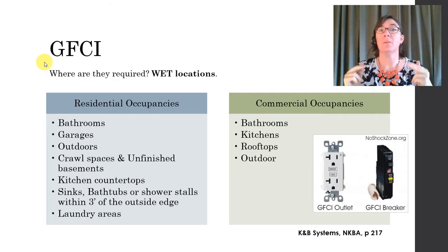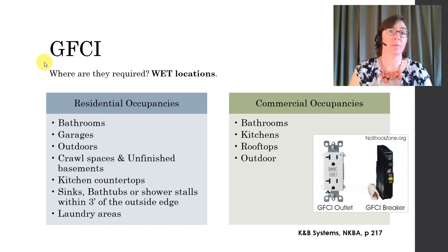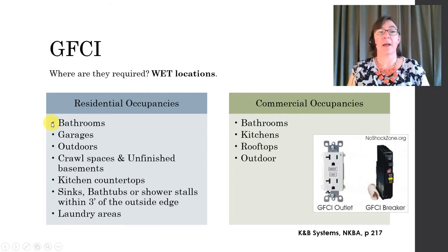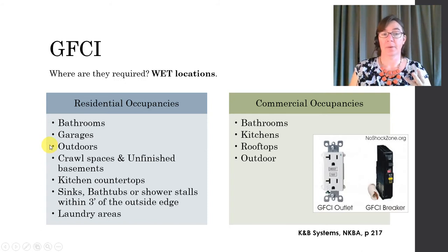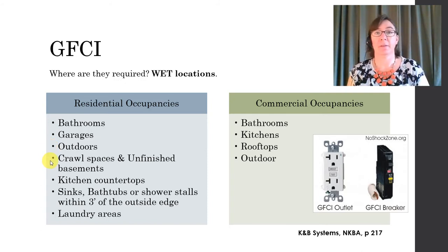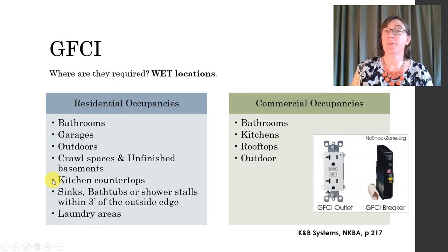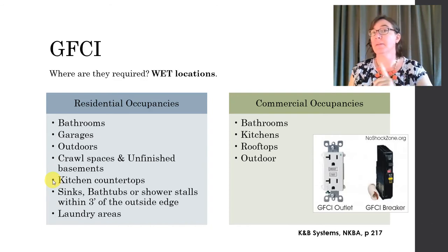They're required in all wet locations. For residential occupancies, which we're mostly concerned with in this class, every outlet in bathrooms, garages, outdoors, any crawl spaces and unfinished basements, all kitchen countertops, but not necessarily other locations in a kitchen.